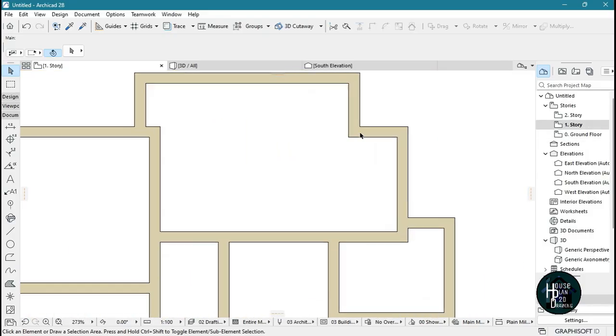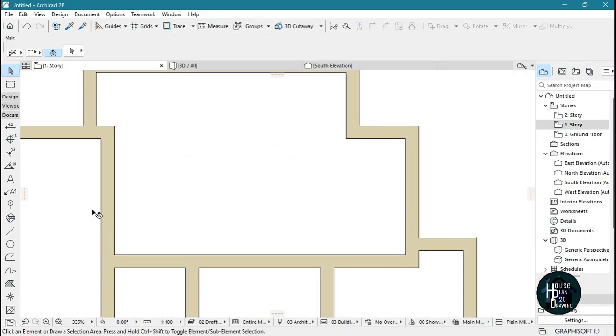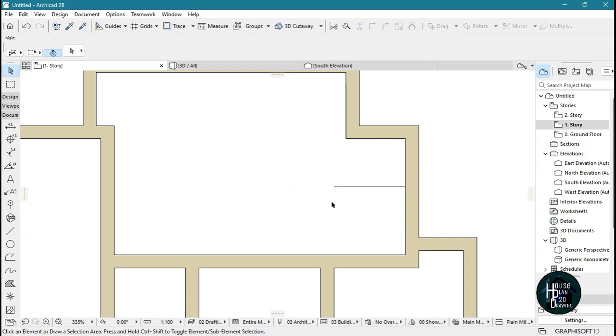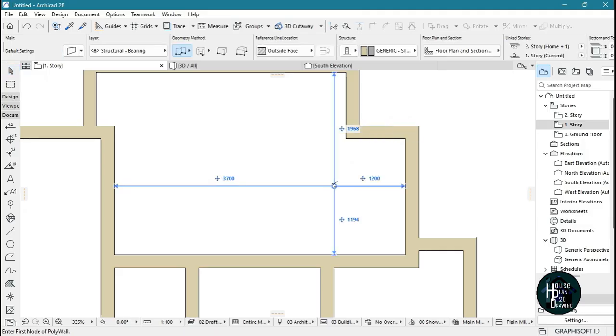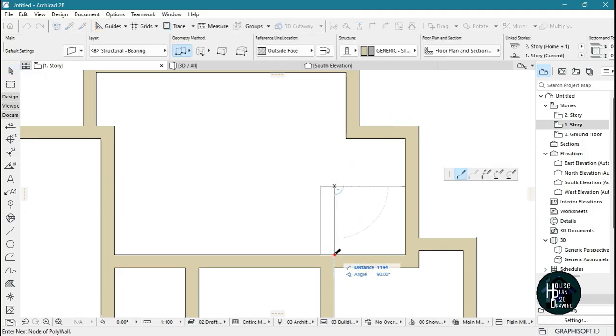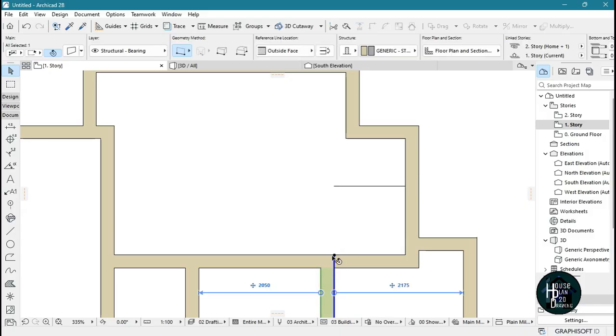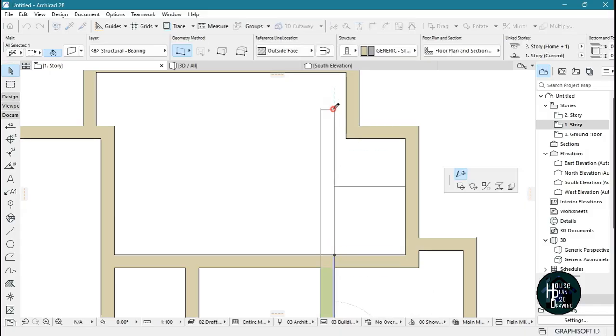Now let's come here, and I'm going to use the line tool again. Click on the line tool, click this point here, drag it outside like this, and we want the distance here to be 12. Click enter twice. Once you do that, hold Alt, select this, click this point here and just drag it to this side here. Or you can start to delete it.